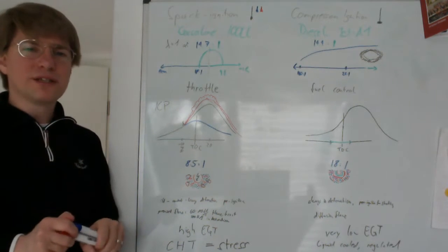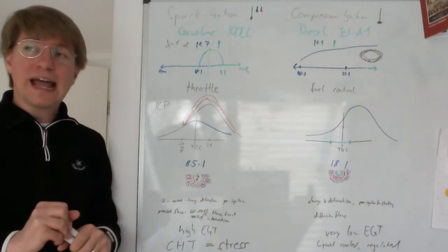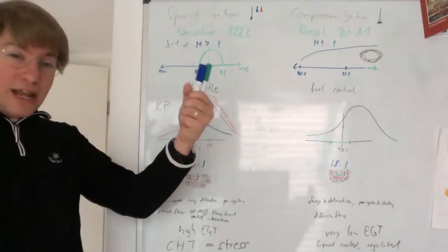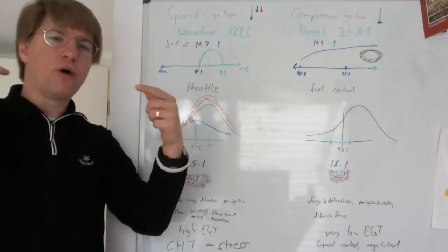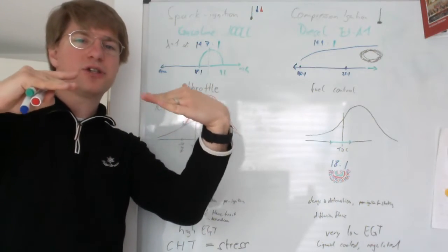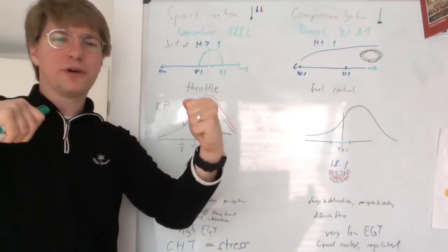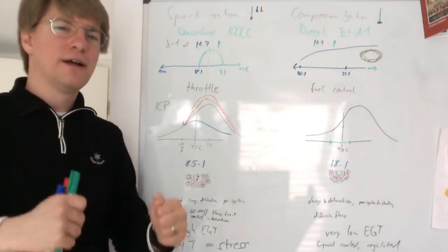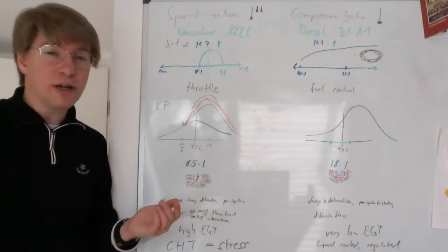You actually want the engine to be in mild detonation if you just put in a new cylinder and you are breaking the cylinder in, because what it does is it raises the ICP, and when you are breaking in a new cylinder or several new cylinders, you want the high pressure to push down on the top compression ring and move the compression ring outward so that the top compression ring is really pushing against the new cylinder wall, scraping it and breaking in the cylinder. So for a cylinder break-in, we actually want to run in mild detonation.